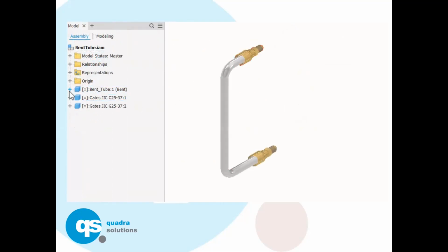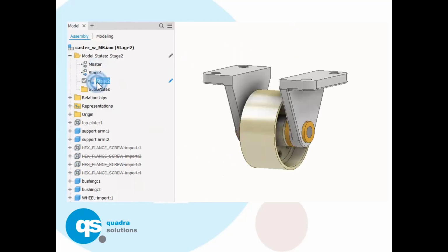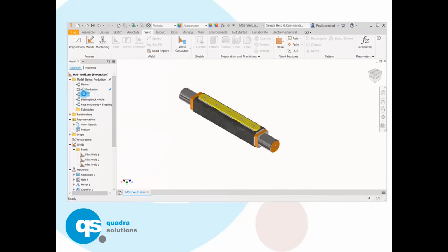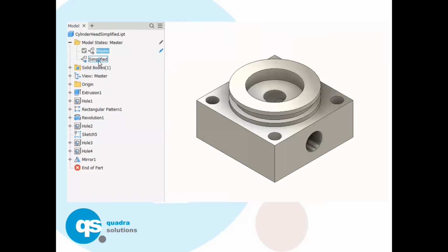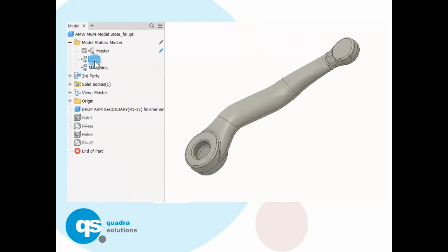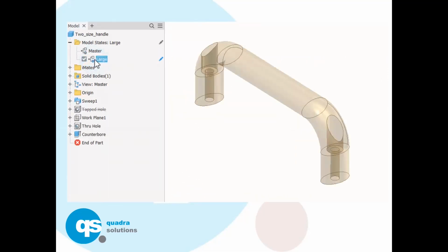So that's one of the benefits of model states. It replaces level of detail and it kills multiple birds with one stone. It does give you configurations so that you can open the machine that's got the touchscreen interface, or the version that's got the dials, or the version that's got, you know, a piece of string and a hammer. It also gives you the performance. You can use shrink wraps. You can use substitute level of detail effectively. You can remove the entire internal combustion engine with 100,000 extra components and swap it out for just one big footprint block, X, Y, and Z cube of the right size. So it gives you the same functionality as level of details, and it gives you the functionality of level of details that they were being used for, configurations and performance.